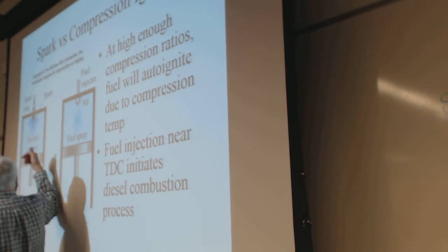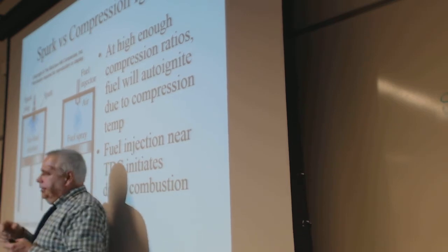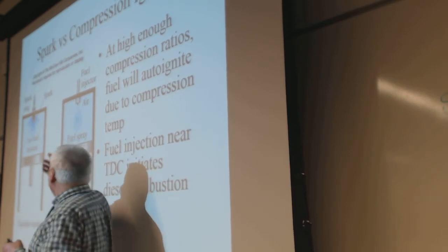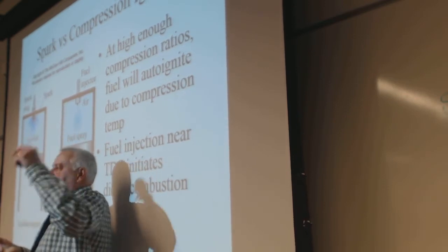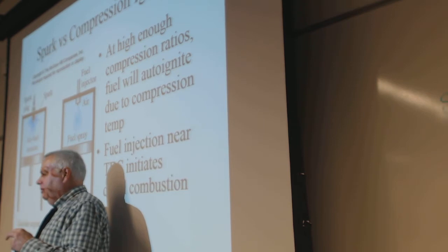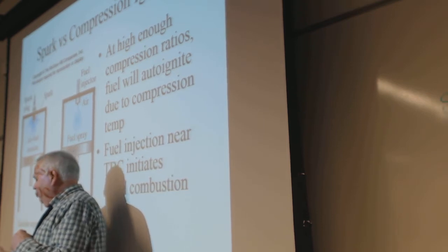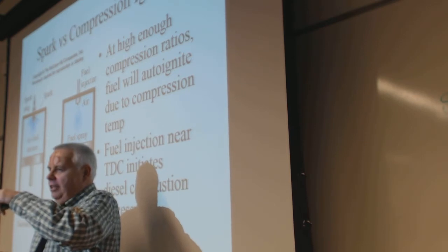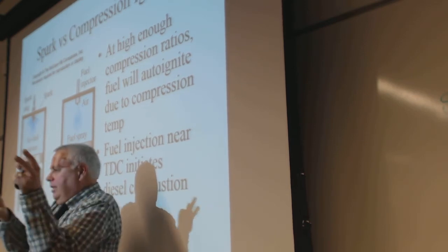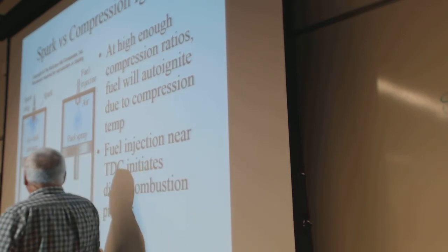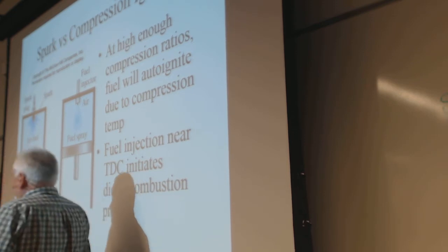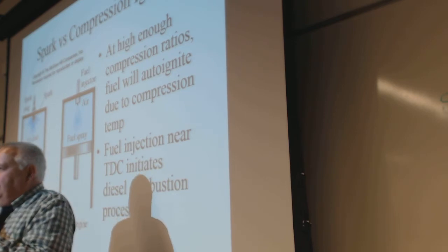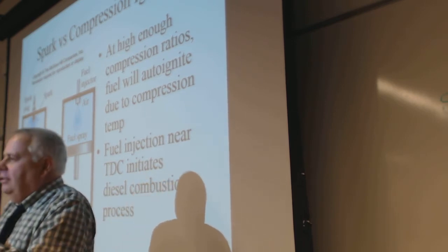But diesels tend to be either free breathing or more commonly turbocharged. So this comes in with a bunch of air. It might even be pushing the piston a little bit. The backside of the piston's atmospheric pressure, and the intake's 10 psi or 5 psi or something like that, then it's going to actually help push the piston. Then you get a full charge of air, and now you squeeze it, and when you squeeze it, it gets hot enough to cause the fuel to burn.